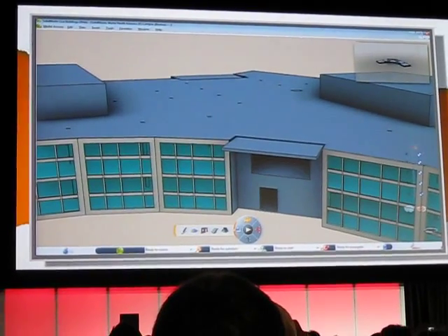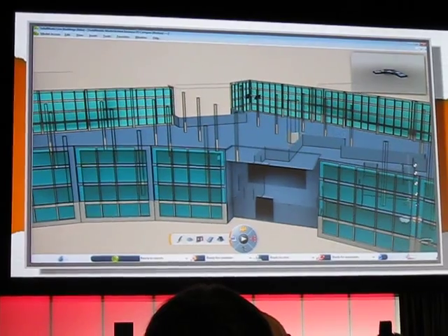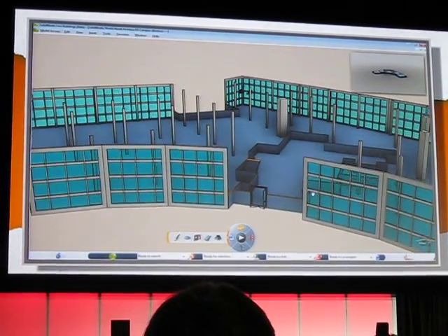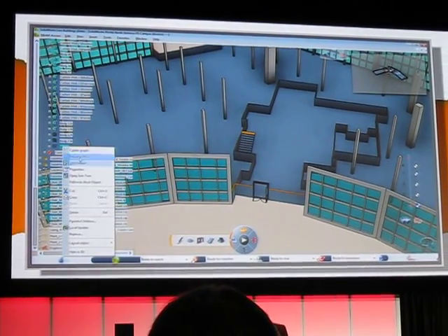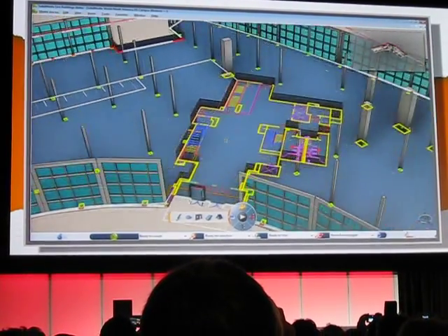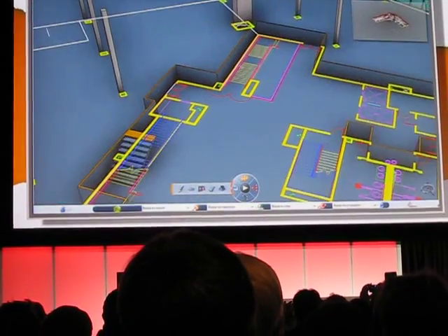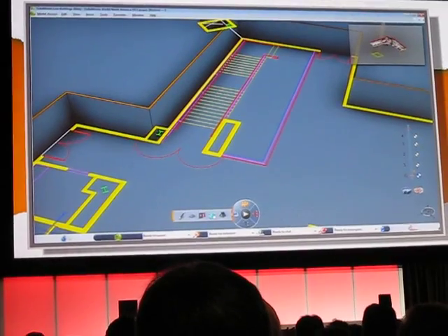We'll go ahead and use this live section tool down the right, which is organised by floors. It makes it very easy to dive into the building to start adding our content. Now, it's typical of planners to design a floor plan in 2D. This particular design was actually designed in DraftSight, so we can take the DWG file and overlay that into our 3D design. It makes it easy to use it as a guide to add content, such as walls and stairwells.